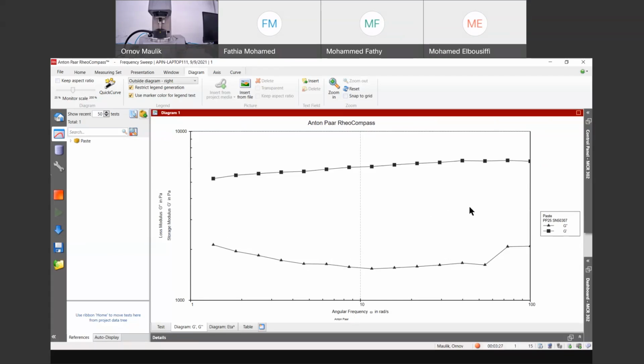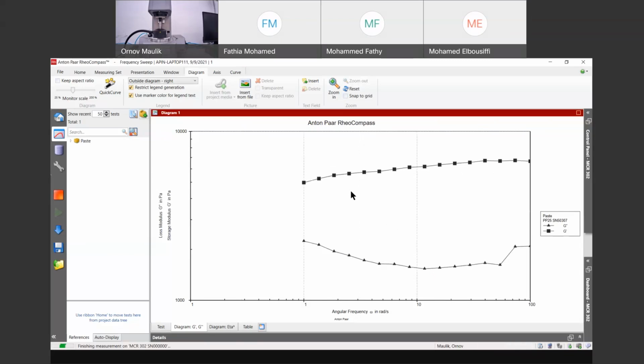So if you have seen the polymer one, it was completely different, where you need to see the crossover point, that is the crossover between G prime and G double prime. Although in this case, you can see there is no crossover. And if there is a crossover, that would suggest some sort of phase separation, which is not desirable for any consumer products that we use in day-to-day life. The crossover itself is not favorable for usage, because crossover would mean the phase separation or physical instability.